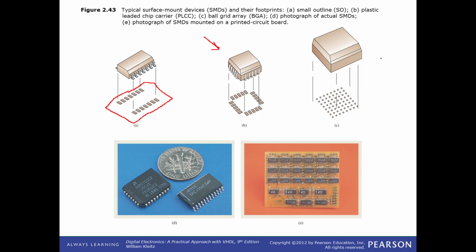And then finally we have a ball grid array, or BGA, another very common type, especially with very high pin count chips, microprocessors that require a lot of pins. They often use ball grid arrays because you can pack, here they show 4, 5, 6, 7, 8 by, I'm assuming 8, yeah, 8 by 8, so that's 64 pins that they can fit in this one area. You don't see it in the picture here, but there are little balls, kind of like semispheres, little domes of contacts underneath this chip in a grid pattern, and those balls come in contact with the metal pads on the circuit board and are soldered to those metal contacts.